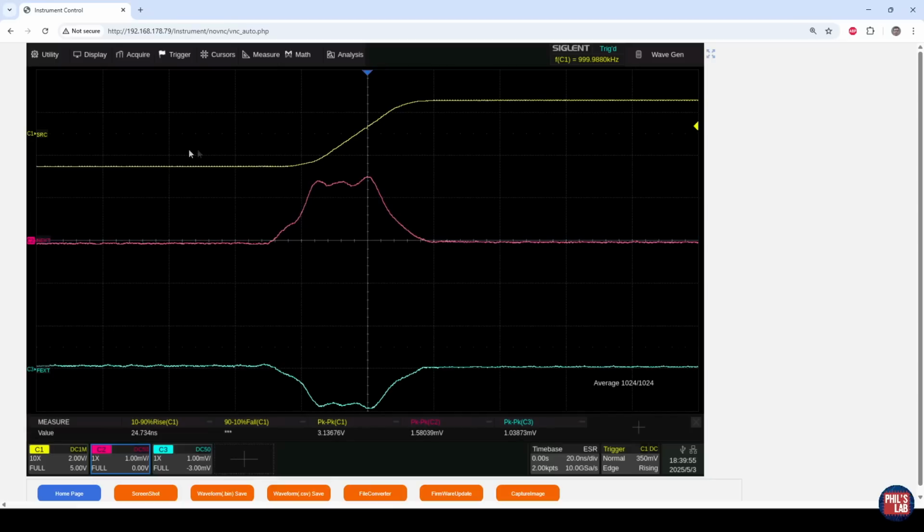and we can see what's going on a bit clearer. On the rising edge of my input aggressor waveform, we can see on the near end crosstalk, we are getting a positive going pulse, which has a similar time width as our rising edge. On the contrary, although the pulse does look similar, for the far end crosstalk, the third trace right at the bottom, this is now inverted. So this is a negative going waveform.